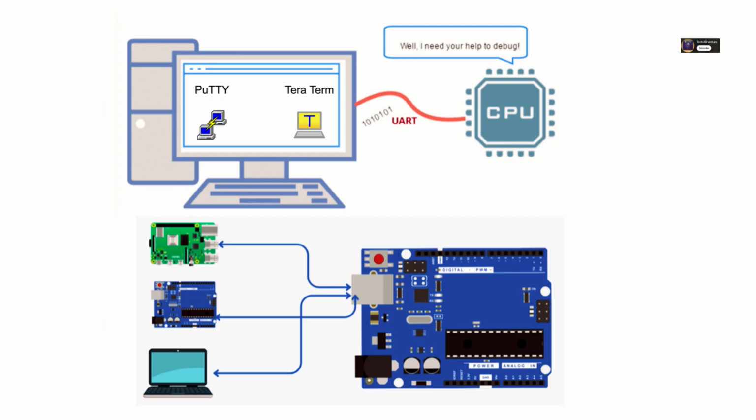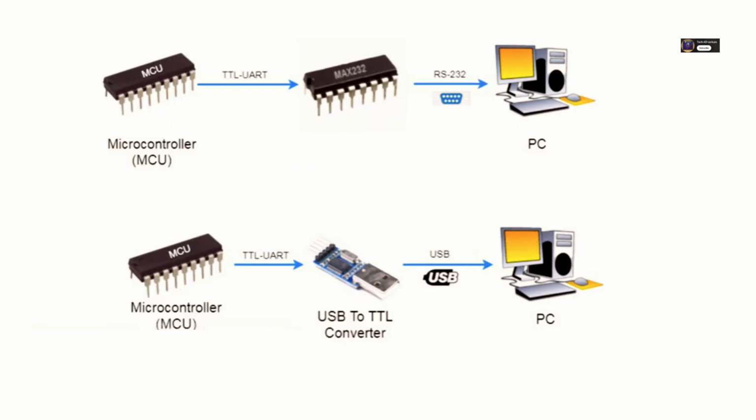And, of course, you need a way to connect your microcontroller's TTL UART pins to your computer's USB port. That requires a USB to UART converter module. Common chips used in these are FTDI FT232RL, Silicon Labs CP2102, or WCH CH340.